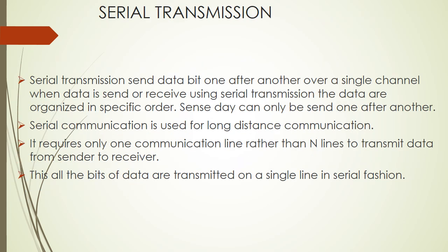So, serial transmission. Serial transmission sends data bits one after another over a single channel. When data bits are sent or received using serial data transmission, those data have to be organized in a specific order so that they can be sent one after the other in a single wire. Serial communication is used for long distance communication between different devices.